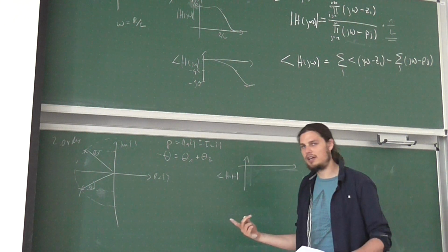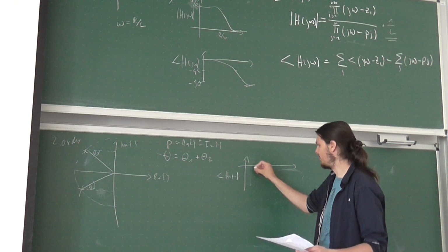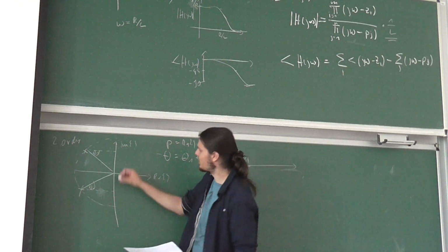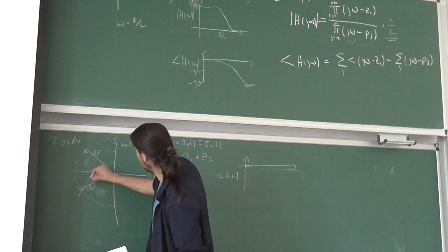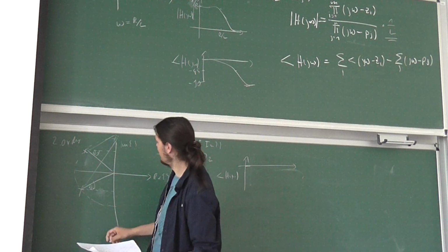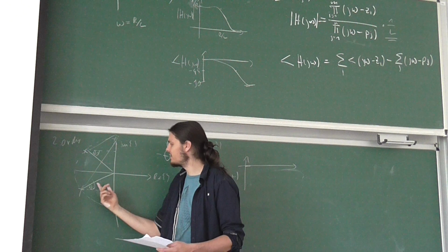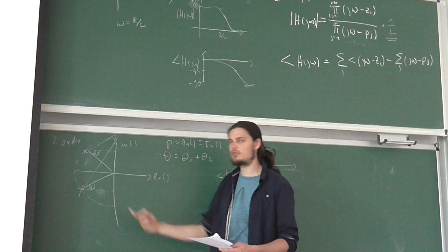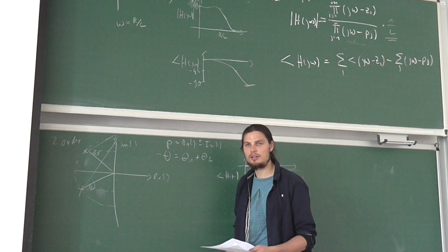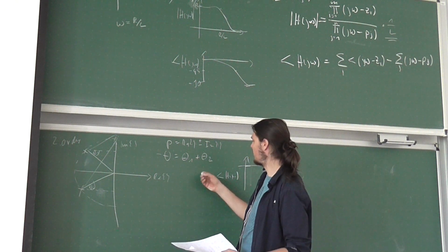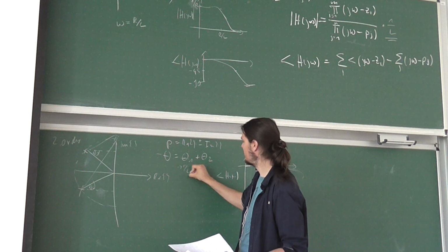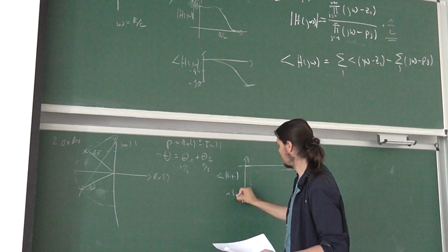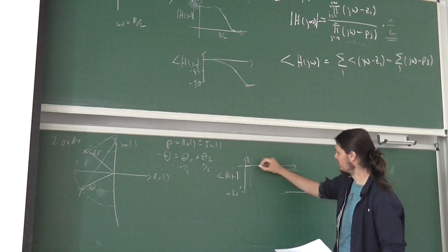So at 0 Hertz we have zero angle, right? And if this goes up, this angle gets bigger plus, this gets bigger plus. What's phi 1 and theta 1 and theta 2 at infinite? Right, so one would be pi over 2, the other one also pi over 2, so we reach minus 180 degrees, right? So that's at infinite.